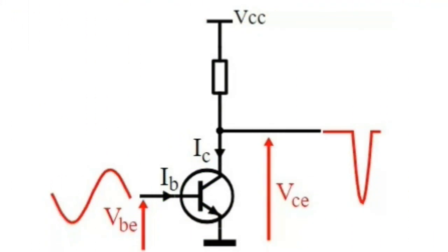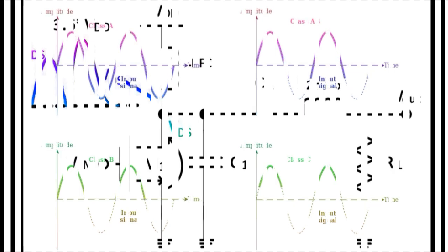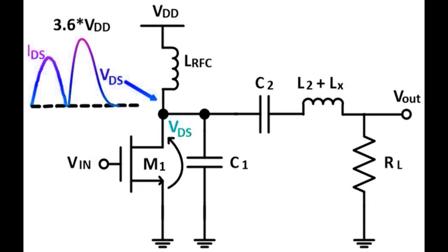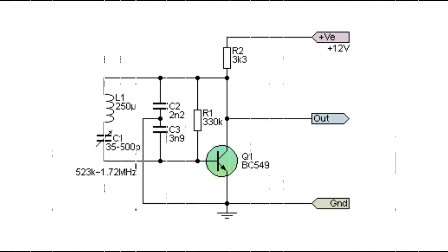Because of their extreme audio distortion, Class C amplifiers are commonly used in high-frequency sine wave oscillators and certain types of radio frequency amplifiers, where current pulses generated at the amplifier's output can be converted to perfect sine waves of a specific frequency. LC resonance circuits are also used in the collector circuit.